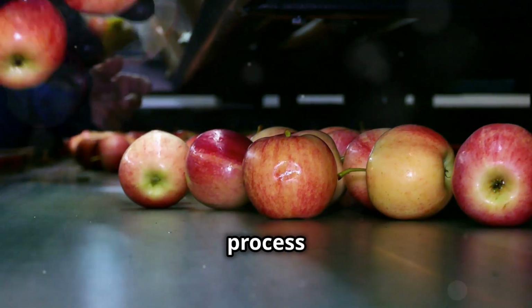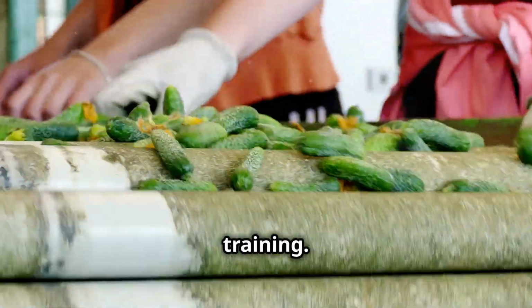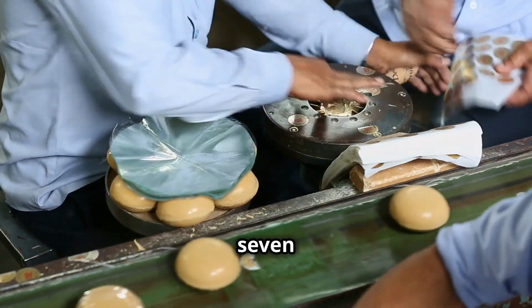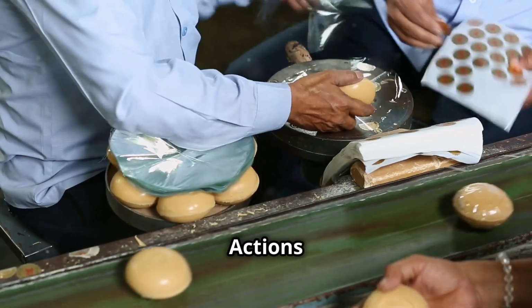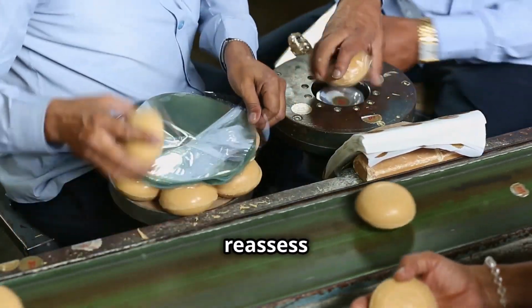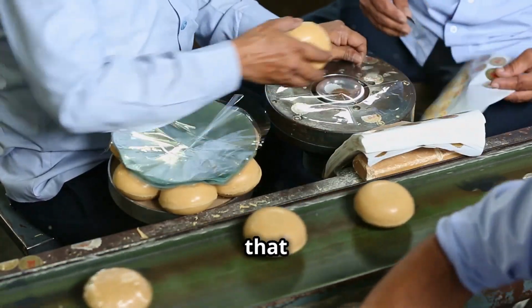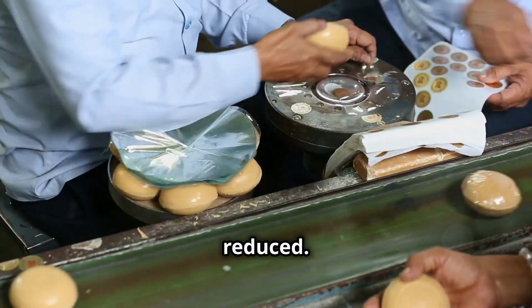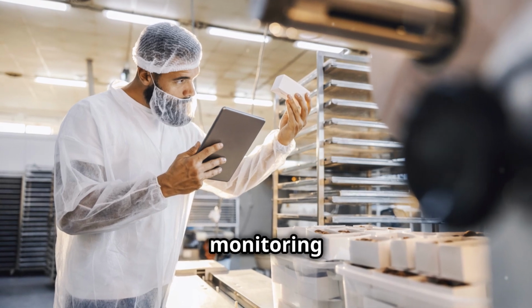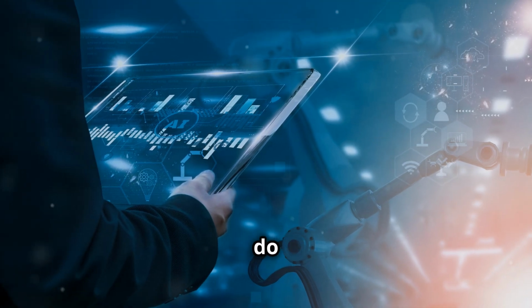This may involve process redesign, additional quality checks, or improved training. Step 7. Implement corrective actions and monitor. After actions are taken, reassess the RPN values to confirm that risks have been reduced. Continuous monitoring ensures that new failure modes do not arise over time.